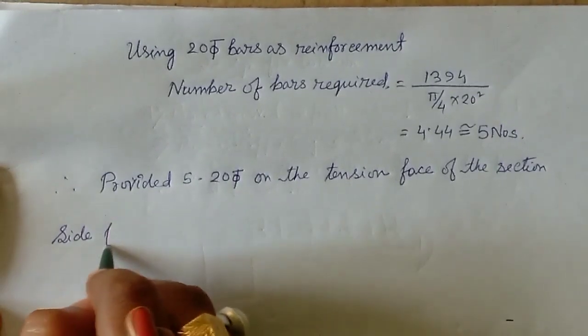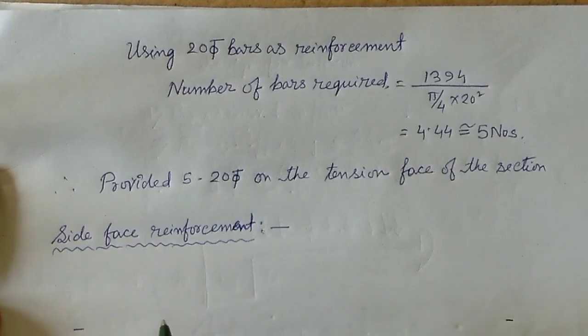Then side face reinforcement. As the depth of the beam is more than 450 mm, the side face reinforcement is required.